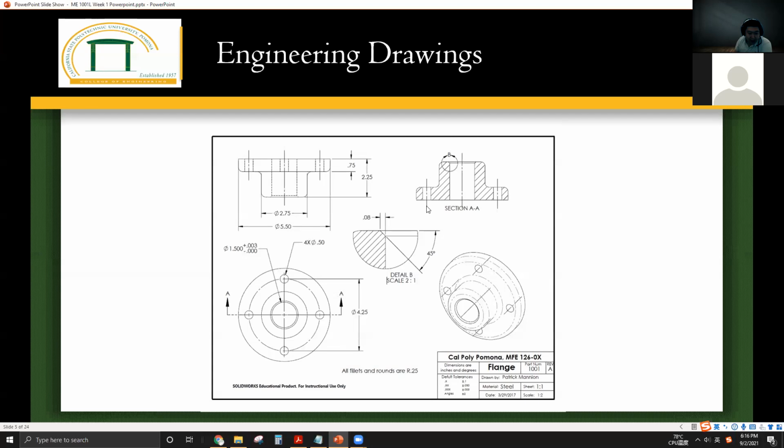And how about this? Right? Most people got it right. It's not an edge line. This is the center line of the hole, or you can call it a construction line, reference line, through hole line. It's not an edge line. It just indicates this is a through hole and this is the center line.